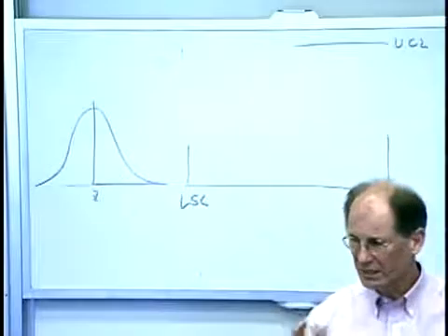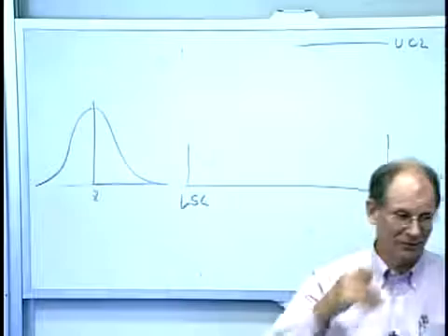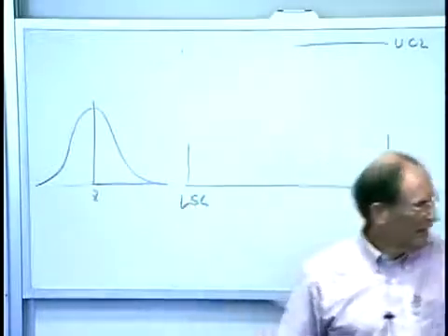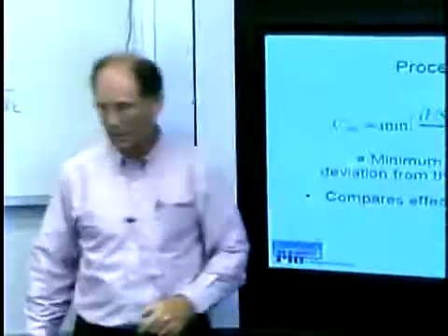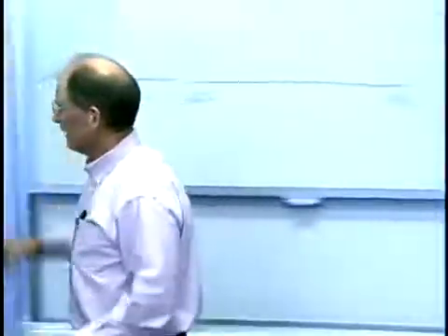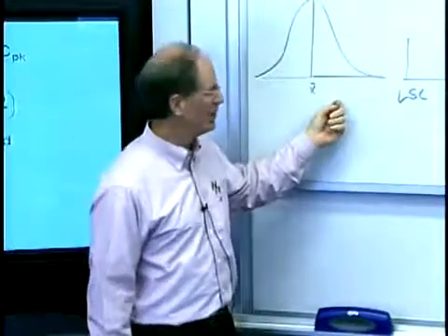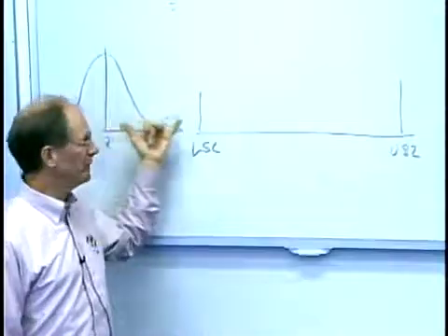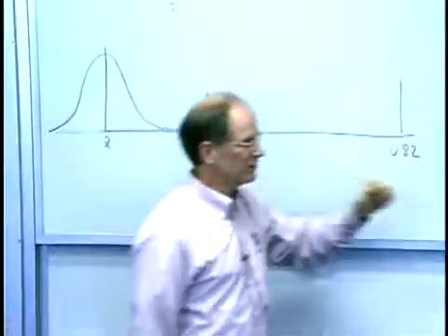it's really only looking at variability. So we come up with this CPK measure, and there are a whole pile of these different ways of looking at stuff. CPK now penalizes deviations from the mean. Okay, so now this would have either a negative or 0 CPK, and if you do the calculation, this is sort of a blend between how well it's centered in here and what the deviation is. So if it's perfectly centered, then these two numbers